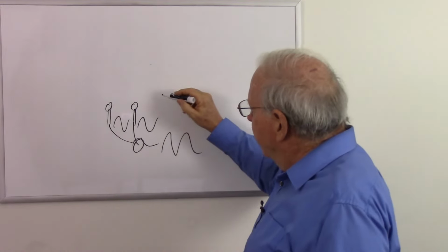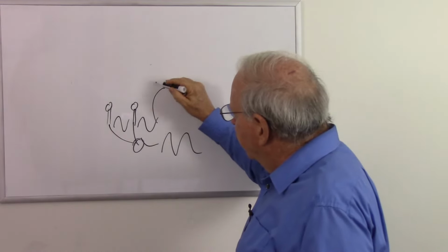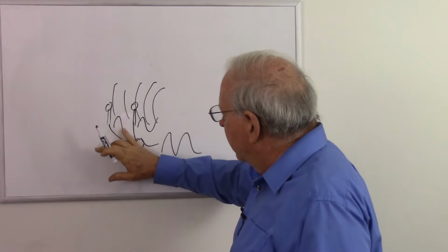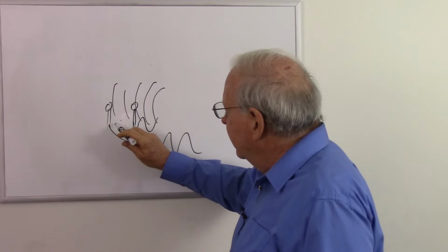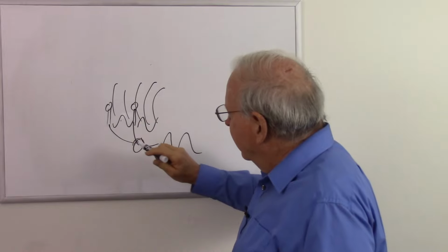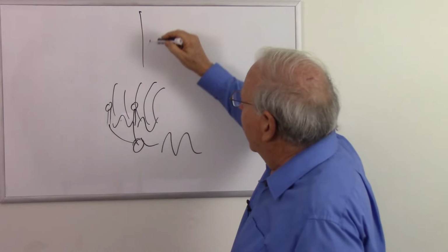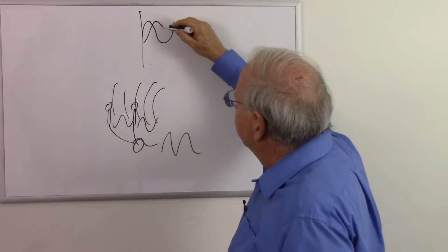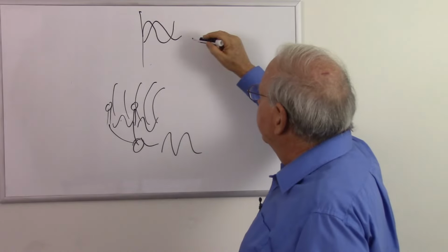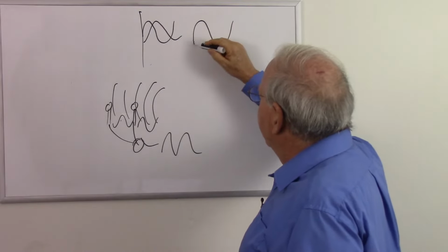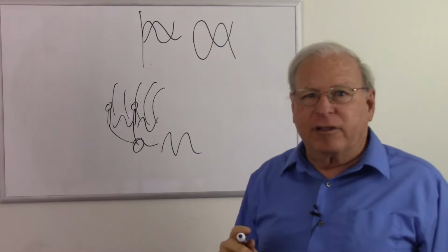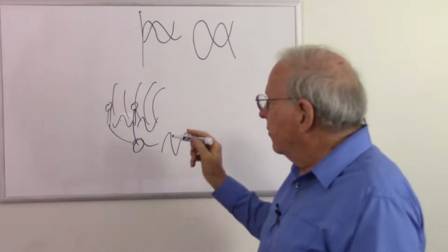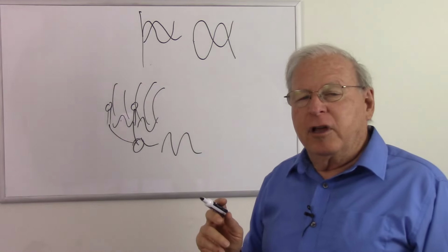But what about sound coming from the side? Well, at the right frequencies, the sound coming from this side here is going to hit that microphone first, then that microphone. That's going to cause a slight delay. If you can see what I'm trying to say there, here's our timing. There's the right microphone and then there's the left microphone, slightly delayed. And if the delay is perfect, the right microphone and the left microphone completely cancel each other out. And other frequencies will somewhat cancel each other out. So that's the purpose of sometimes using two microphones.